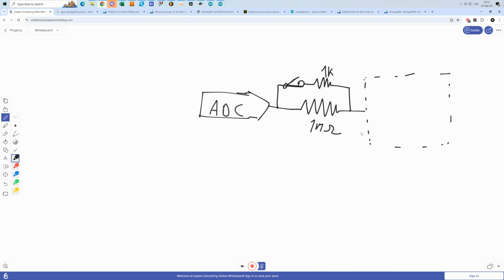So this is why when you are using an ADC, I always recommend to put just a very tiny capacitor over here, a very tiny one, for example, 1 nanofarad, just so that the voltage doesn't drop, so that the ADC has somewhere to draw the current from. So this is also an issue that you can come across. So use just very tiny capacitors when you try to sample a signal with an ADC.